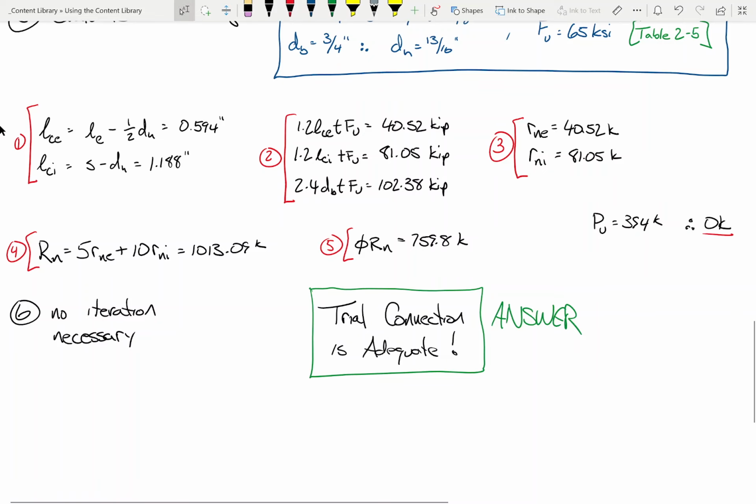Does it make sense why we arrange the bolts one way versus another? Because we want the connection to be as tight as possible so we don't have to waste material with plates. Every connection has plates that go along with it. It might sound silly, but that stuff adds up.